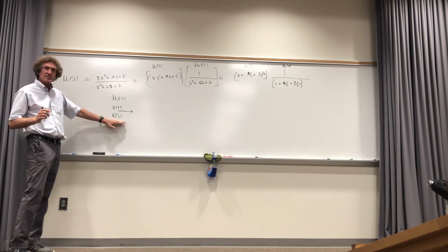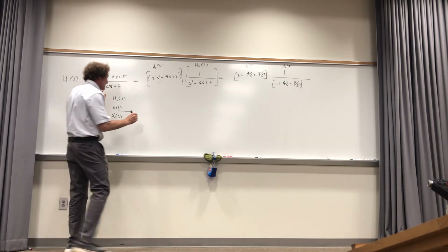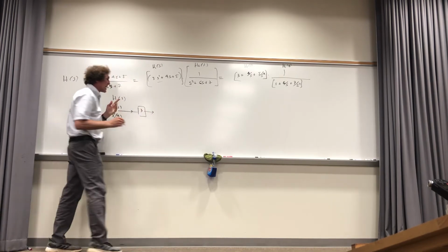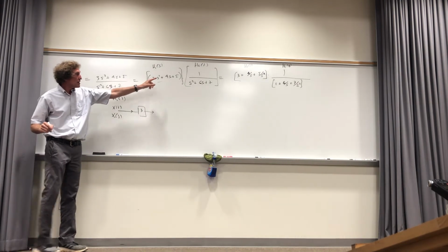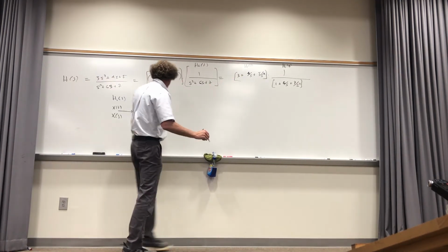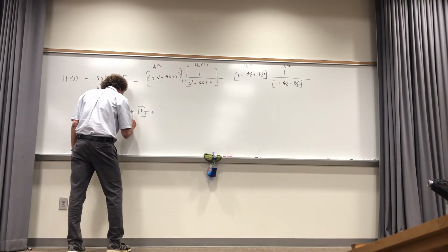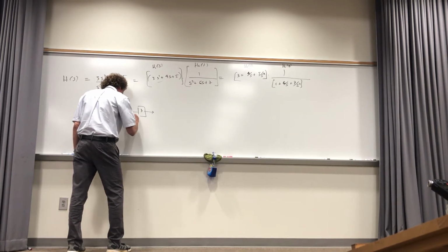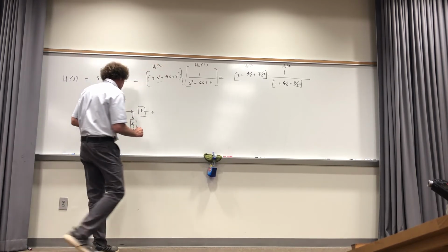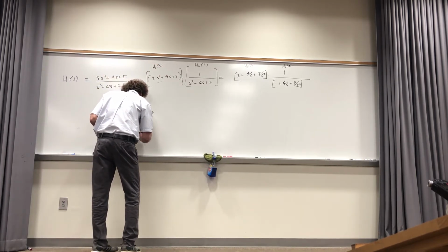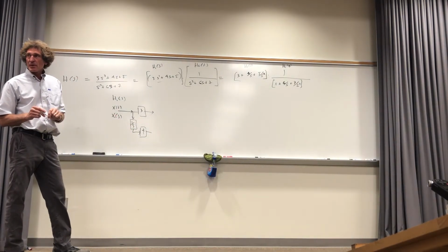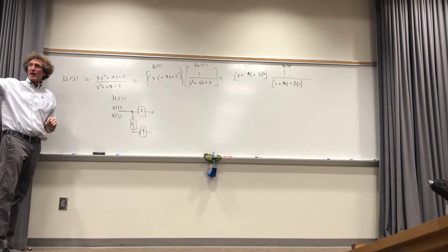Think of the s domain, x of s. It comes in there, and right off the bat I see a 3. So I put a 3 here, it's a block. It just means it's going to amplify that first part by 3, right here. With me? Now I need a 1 over s. So I come down here, and I have a 1 over s block. That's the flow of the signal. And then that has to be multiplied by 4. We know we're going to add these together in a second. Does everybody see what I'm doing? Can you all see it in the back, far back?